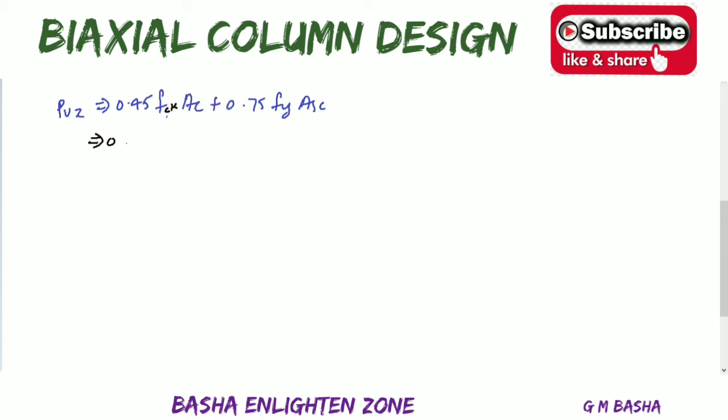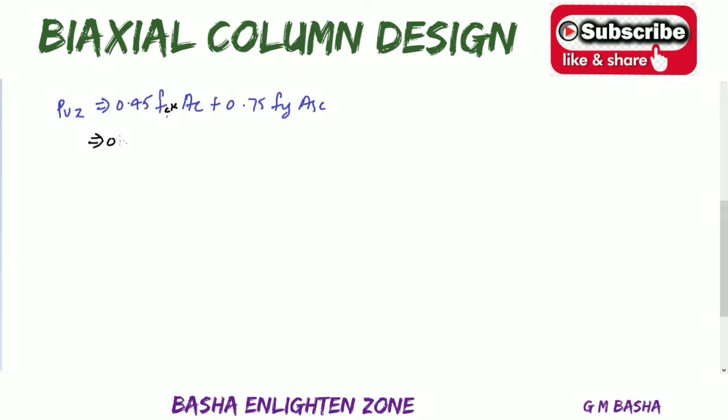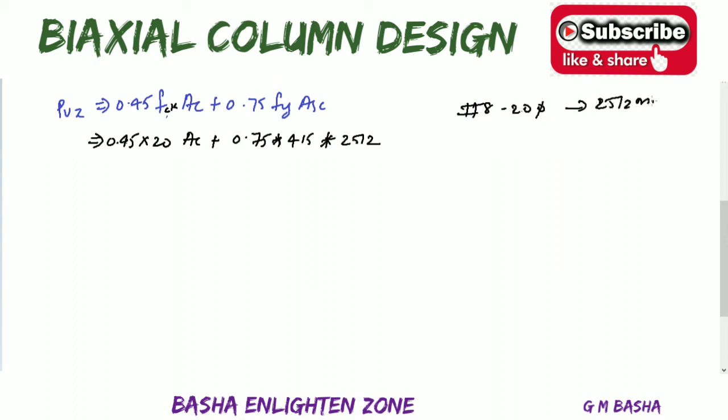Check once whether you wrote correctly or not, which is FCK, AC only. Okay, so 0.45 into FCK will be equal to 20, again AC is unknown here, plus 0.75 Fy is 415, and what about area of the steel? Area of the steel will be 2512, what we provided for 8 bars of 20 dia, which is equal to 2512 mm square. And again, what about AC?